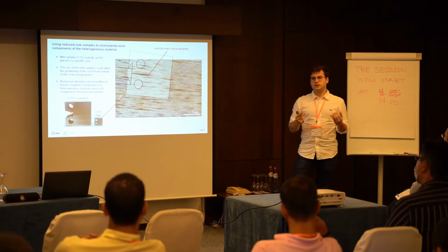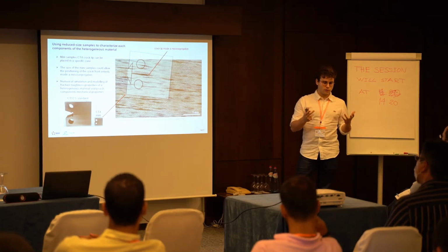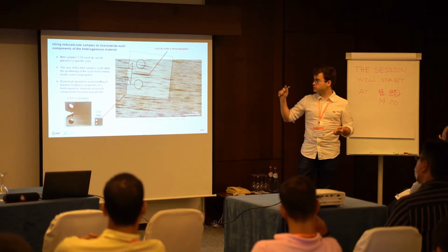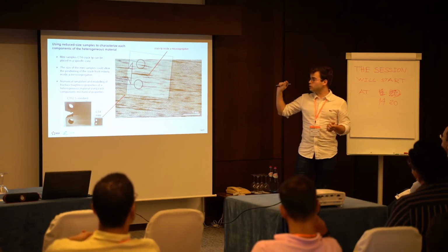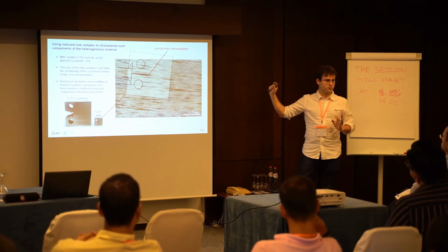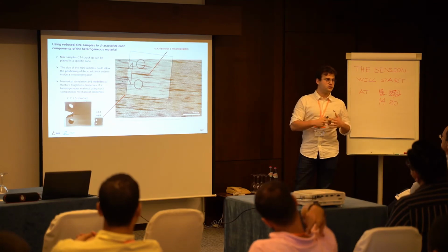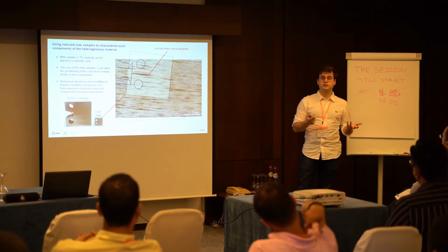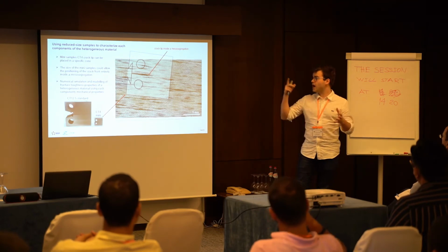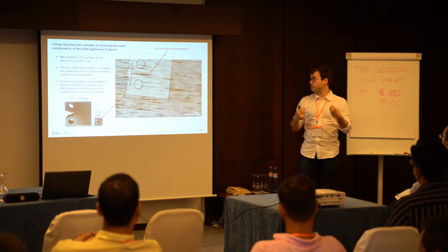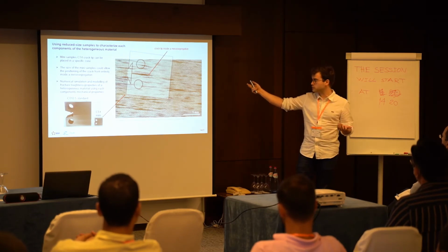And then it's like measuring the properties of both components separately, because the process zone of the sample at fracture is smaller than the thickness of the meso-segregations. And thanks to numerical simulation, you could build a model that calculates the stress field inside the highly segregated material, considering the heterogeneity of mechanical behavior of both components.